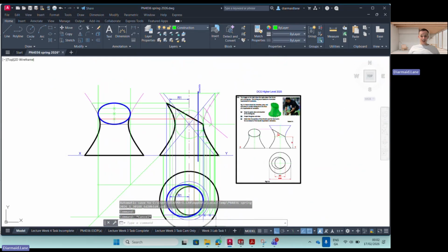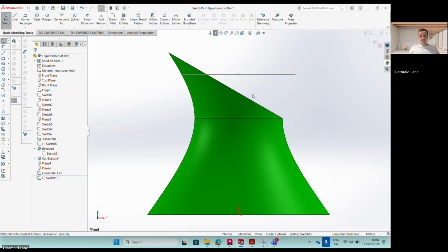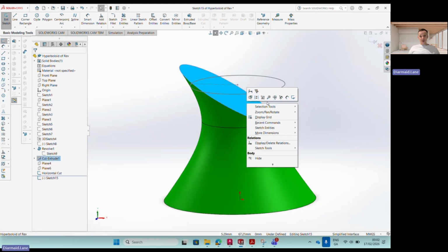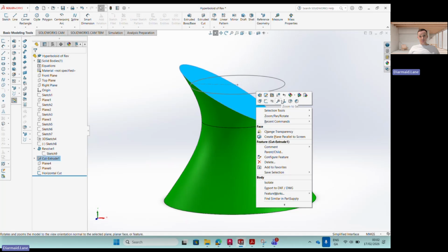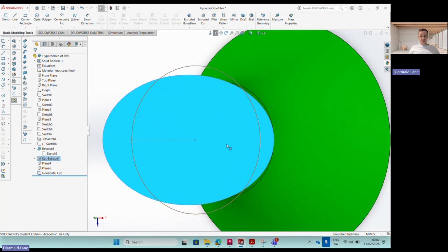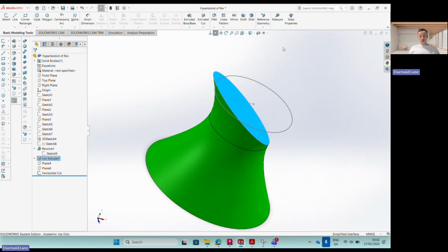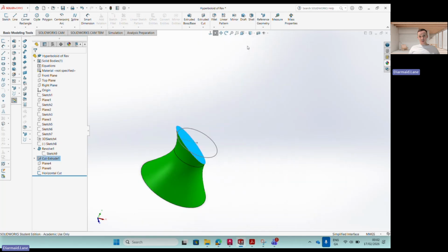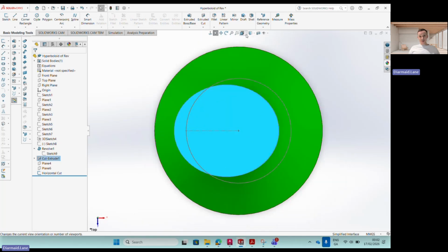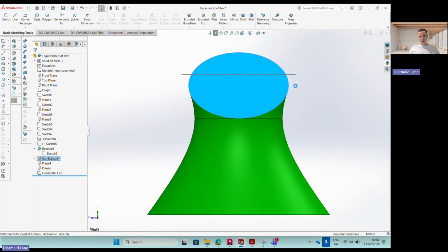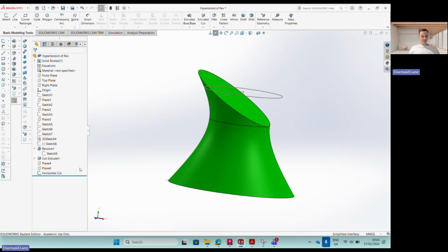But what that creates is a surface. If I look at that surface perpendicularly, it is always an ellipse, and they are just versions of that ellipse. When we look at it in plan view, it's also going to be an ellipse, and in end view, it's going to be an ellipse there as well. Obviously it's not the true shape of the cut surface, but the projection of an ellipse is always going to be an ellipse as well. All right, so that's it. I hope that's helpful.